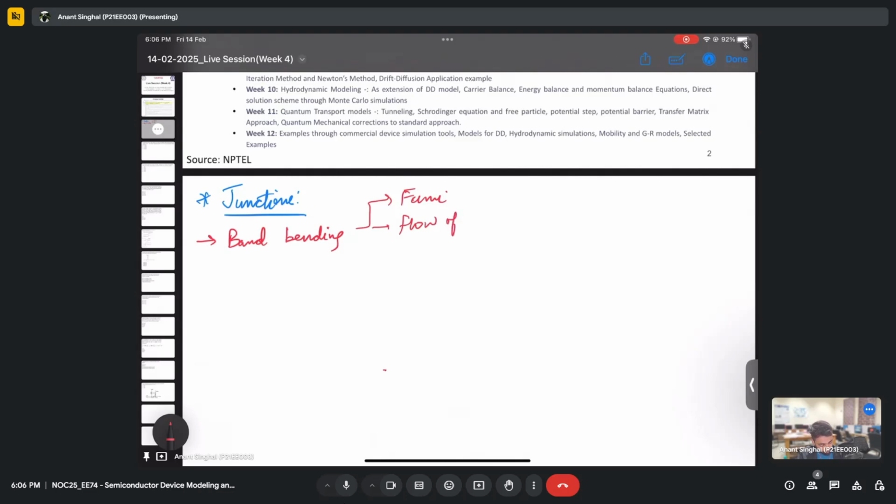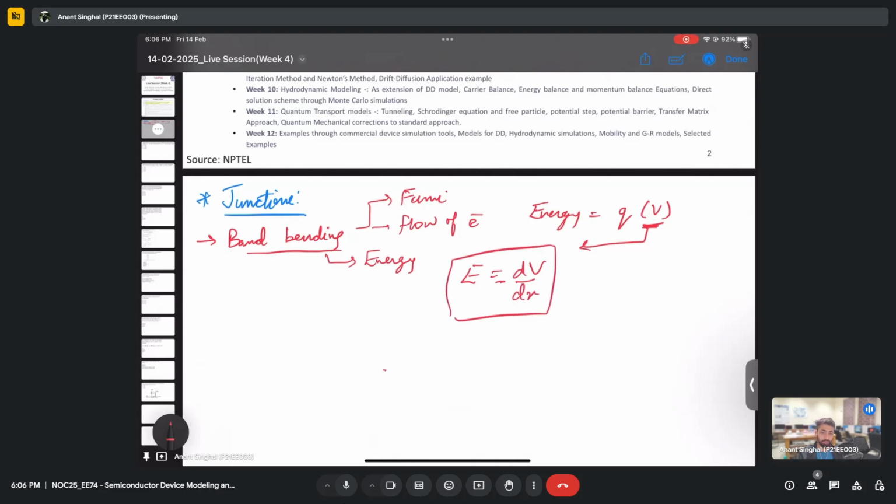Yeah, that is good. So basically, first of all, as we have already established, these band diagrams are energy band diagrams, and we know that energy, in very basic terms, is nothing but charge times potential, right? So band diagrams are also a measure of potential, and once we know the potential, we know the electric field, right? Electric field is nothing but the gradient of the potential, minus dV/dx. So band diagrams can help you analyze anything, such as the potential profile, which is this V, such as the electric field profile, which is this E, etc.